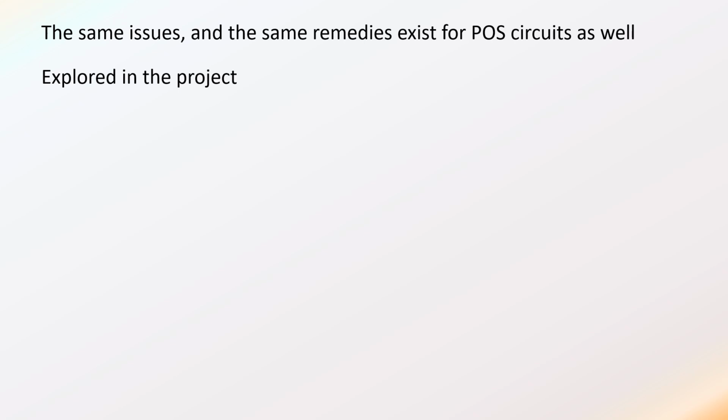But I want to reiterate that the takeaway is that for any combinational logic circuit that you design, as part of the project in this class or going forward in your design life, anytime an input changes state, you should suspect that immediately after the input changes state, one or two or all of the outputs might have a glitch unless you prove otherwise.